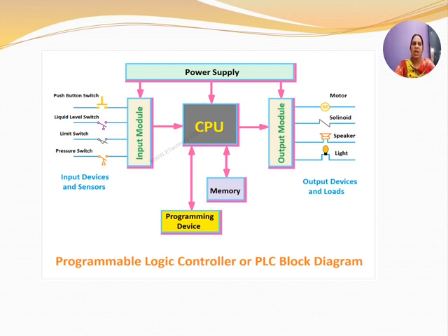The main advantage of the PLC over hardwired control systems is that they are programmed. In a hardwired control system, you are essentially having to rip out the wires and start from scratch, which is more expensive. I would like to give you an example of why we need PLCs. Suppose you have a light connected to a switch. In general, the light operates under two conditions, on and off.